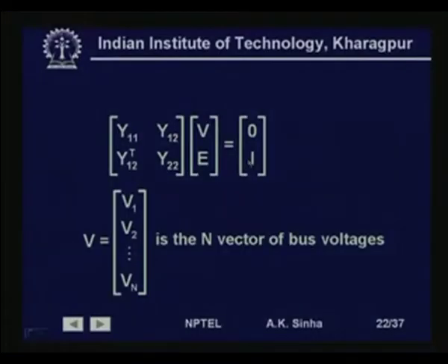generators into the system. Now, here this term, that is the current injection at all the other buses, are assumed 0. Now, this happens because what we do before we try to solve this system is we consider all the loads as constant impedances or constant admittances. That is, we first do a load flow analysis, we know the terminal voltage of all the buses.